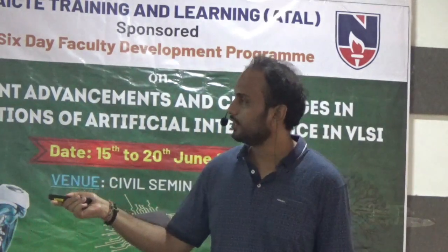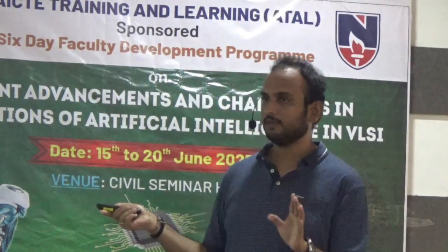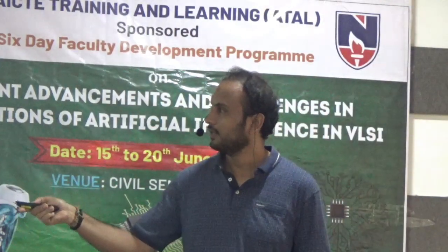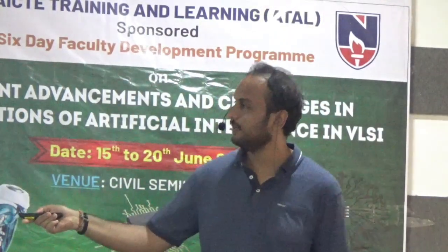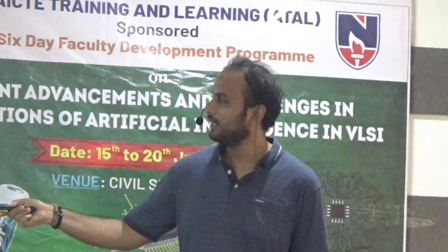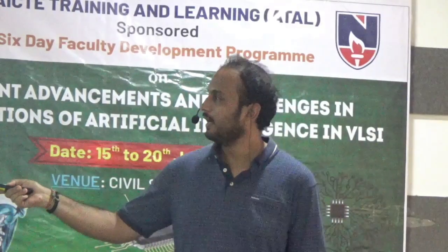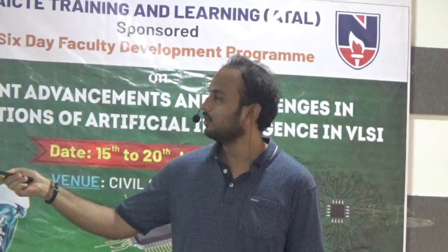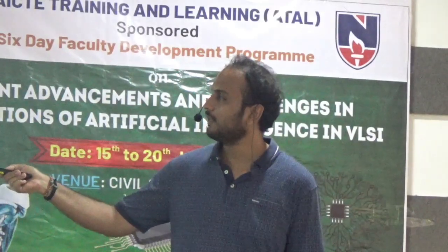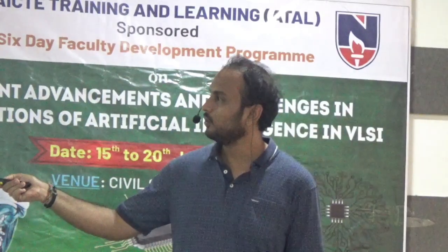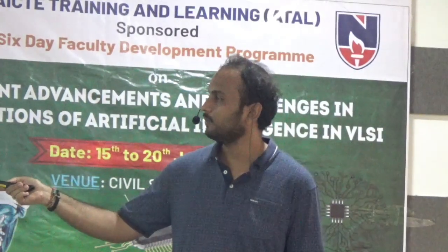If you see, the threshold of all these three technologies is almost fixed. This is the same. The threshold is a very fundamental limit, so we can derive it from the equation. This is fixed. Now when we go to the lower technologies, you will see that we can achieve higher gm. On the contrary, with the longer devices, we are getting lower gm, as we discussed earlier. But what is the trade-off?